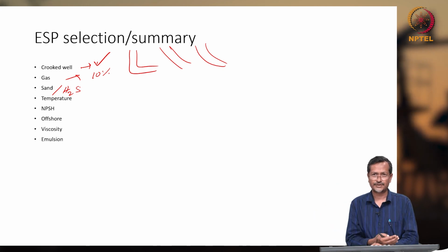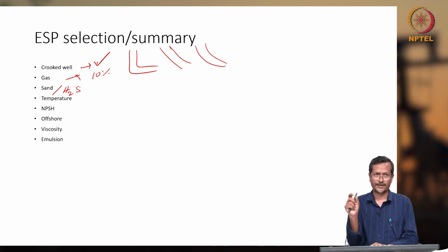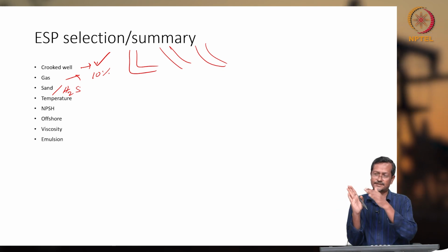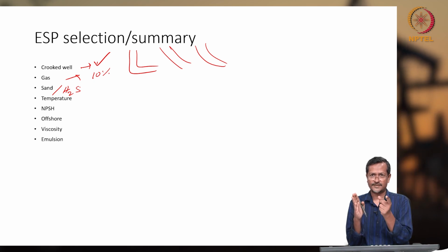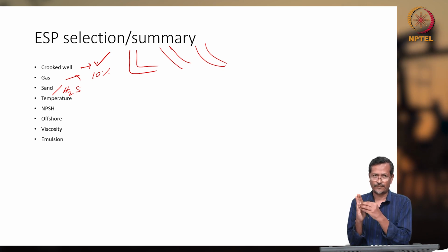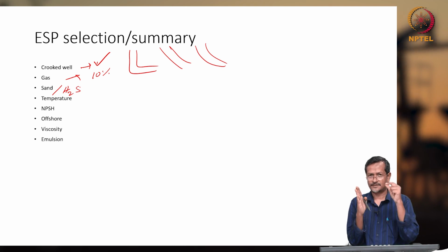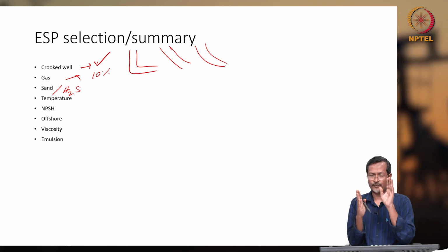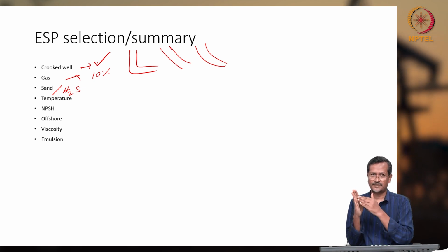I think you have seen in the previous lecture, a metal oxide or metal sulfate or sulfide will form, a softer material. Fe plus H2S gives FeS, so an iron sulfide surface will be formed, which is softer than the metal, iron. Now when sand particles hit the surface, this soft material will get removed. What will happen? The metal will get exposed to H2S, hydrogen sulfide, again.